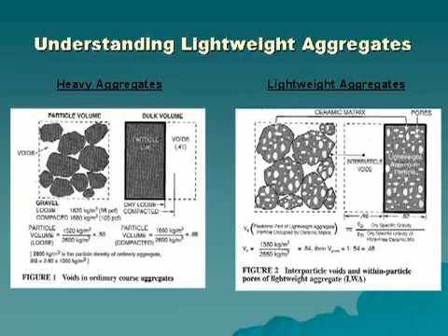Please consider for a moment the volume allocated to the cement mortar, and that it is similar when comparing normal weight concrete to lightweight concrete, assuming both samples being compared are of a similar size and gradation. The shrinkage of all concrete generally takes place within the interparticle void system, where the Portland cement mortar is used. That is why the potential for drying shrinkage within concrete exists within both classes of concrete.